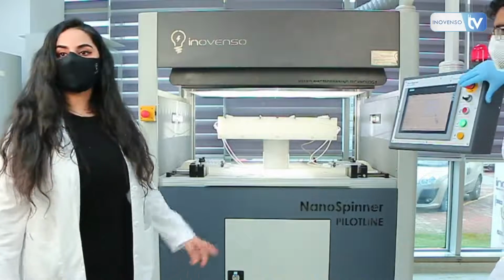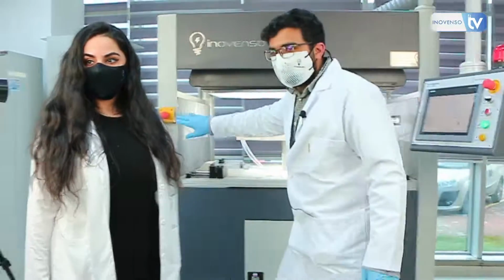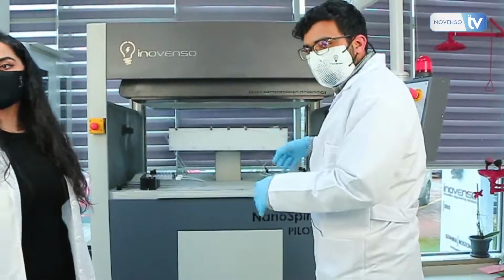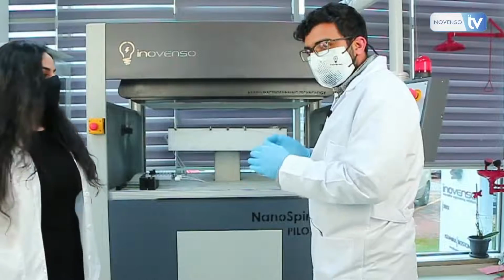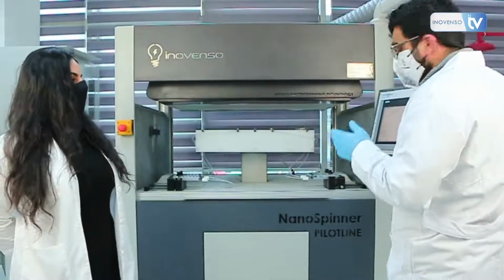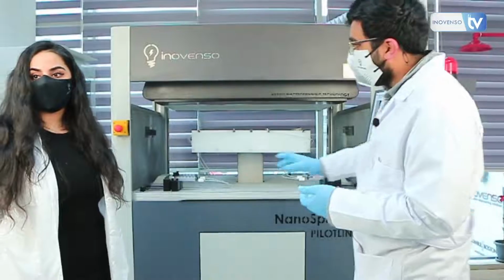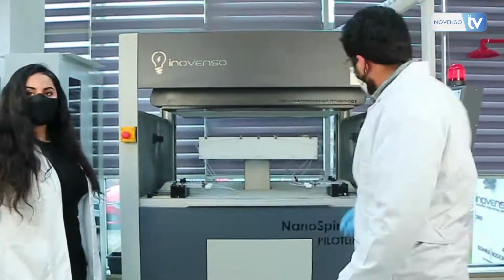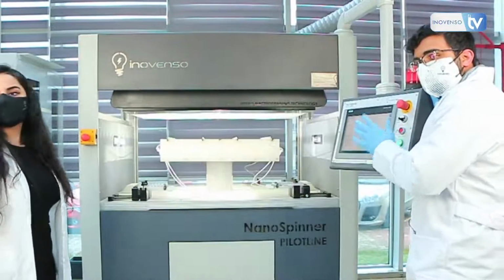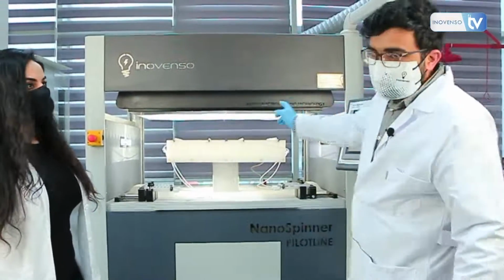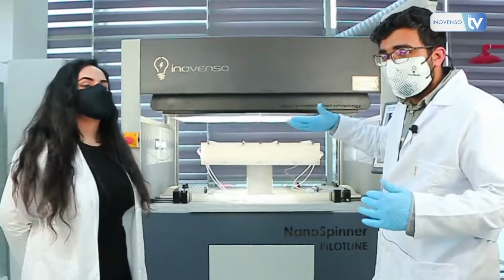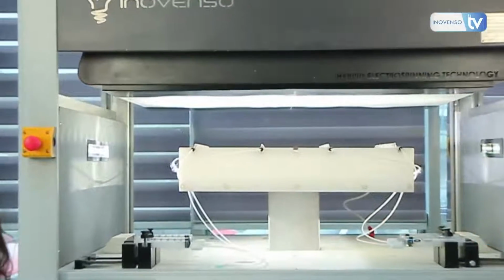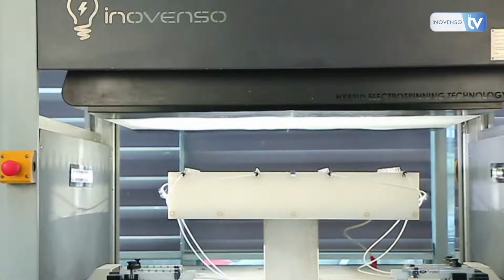Yes, we can just show you the touch panel. Or alternatively, you can press it from here. And let's just see what happens when I press it. The high voltage supply is off, the lights are off, everything is off. This is the emergency button. Afterwards, you would want to activate it again, in which case you have to release the emergency button and then press the reset button here at the control panel to make everything start again. And what you're seeing right now is the homogeneity collector reorganizing itself to its center point, so it can be recalibrated, so to speak.